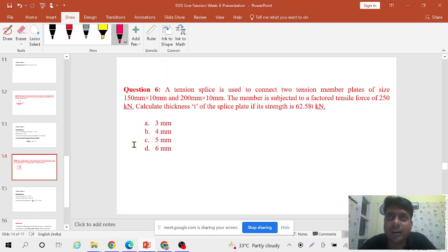See, actually, these are prefabricated members. When you purchase anything from the market, in the case of concrete there is no problem. You can prepare as much length as you want at the site. But these things you have to purchase from the market, and then they must be transported. So for ease in transportation, manufacturers limit the size of the members.